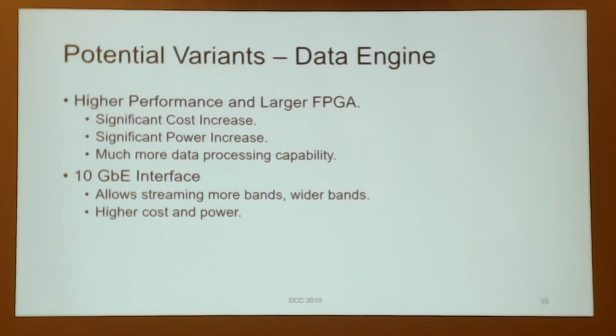We'll down convert it, decimate it, reduce the bandwidth, improve the dynamic range, and the FPGA does all of that processing so that the data that's sent over to the single board computer is a much, much lower data rate and is something that we can affordably throw onto disk to record events.